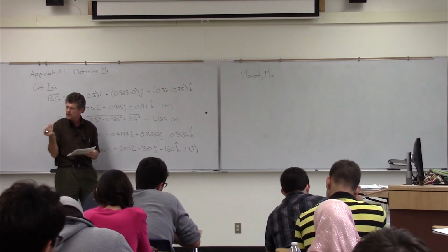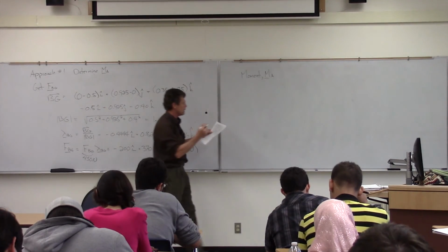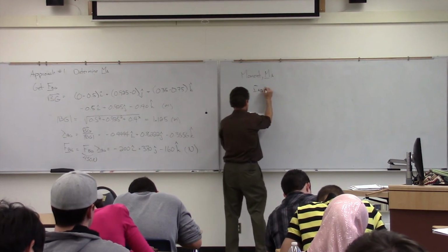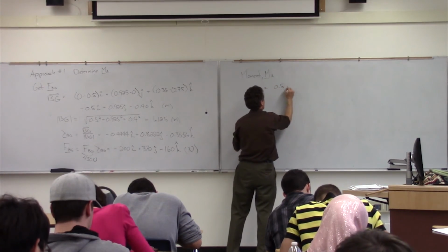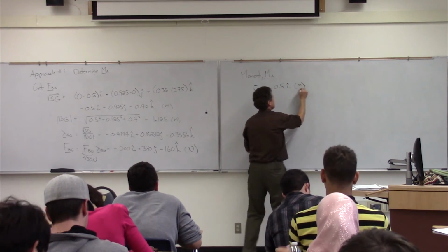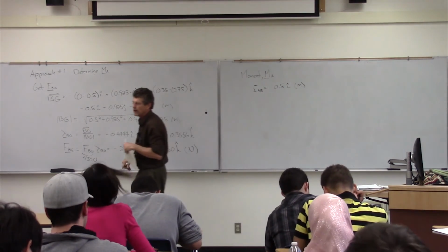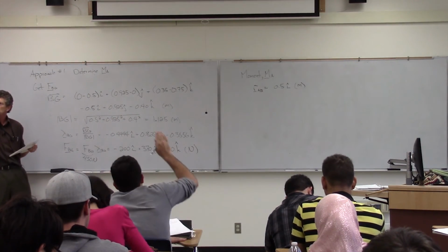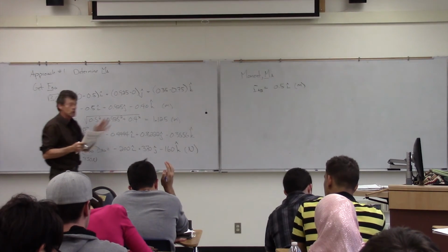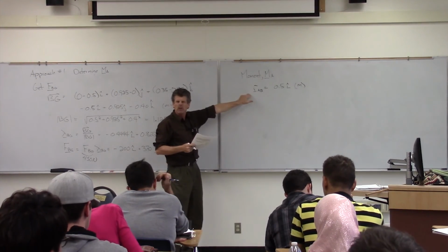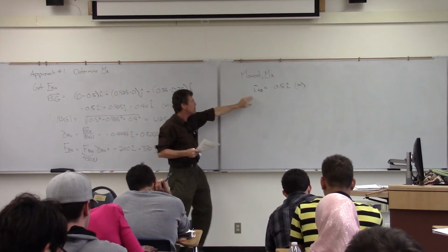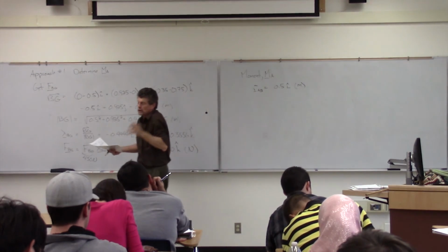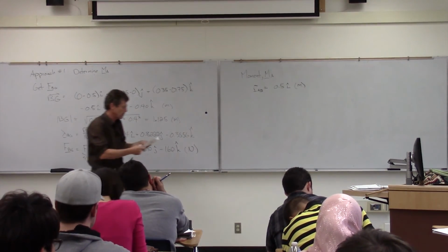Now, we probably want to do B because we can add a lot of zeros in there. Note that if I do R AB, it's just 0.5, a half a meter in the x direction. Now, we could do it at G, and actually, I want you to try that at home. You should get the same answer. But again, we try to find a position vector from my position A to one of those points on the line of action. The only 2 points I know are going to be B and G. I picked the simplest one there.